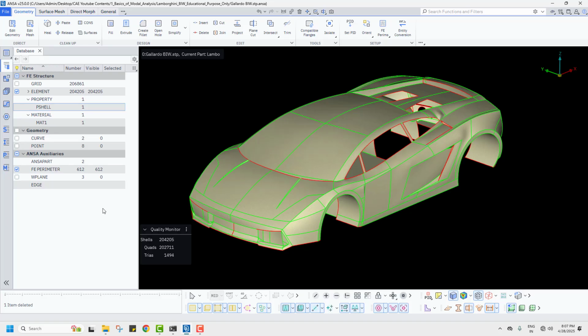There are no forced load cases or boundary conditions for this model, just a free analysis, to see how the model is behaving. In the automotive industry, the first 6 degrees of freedom should be 0. They should move, and from the 7th onwards it should restrict. All the first 6 degrees of freedom should be the same.